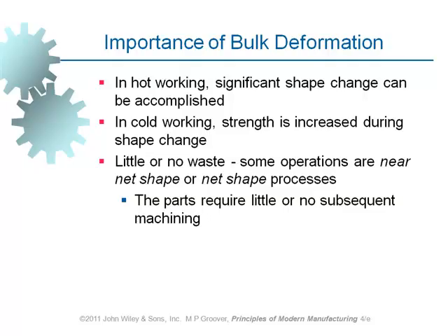It's easier for us to change the shape of the material. Reason, there is a need for less force in order to change the shape of the material when it is at elevated temperature. Generally, when a material is elevated to a temperature above recrystallization temperature, we call it hot working. Do we know anything about recrystallization temperature?